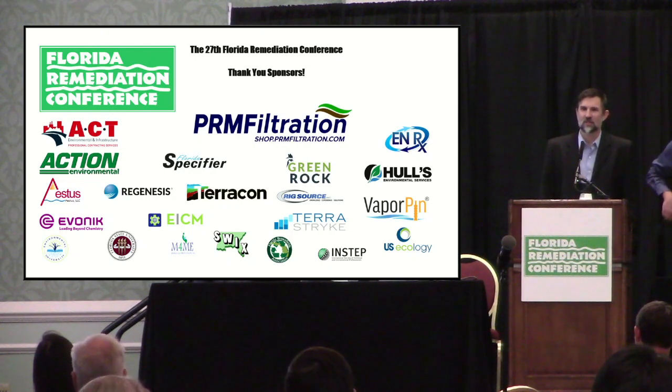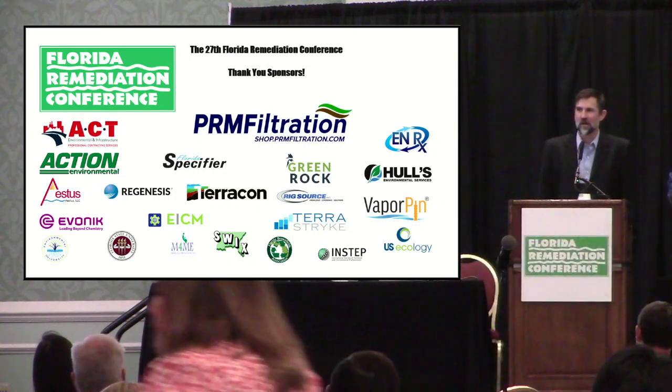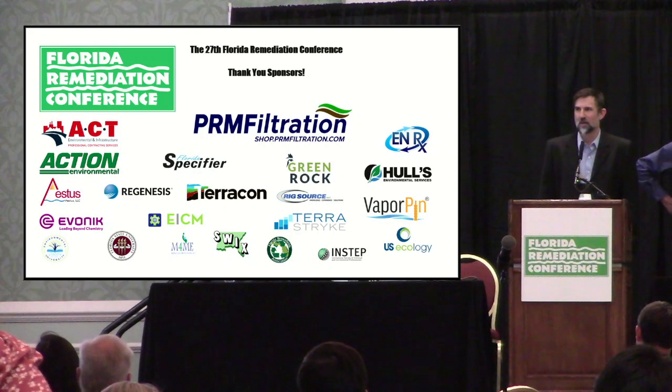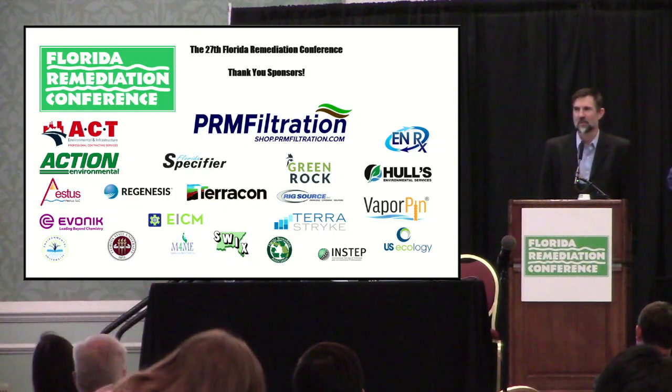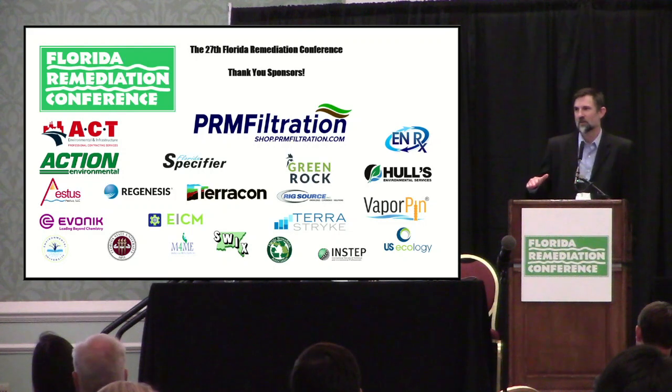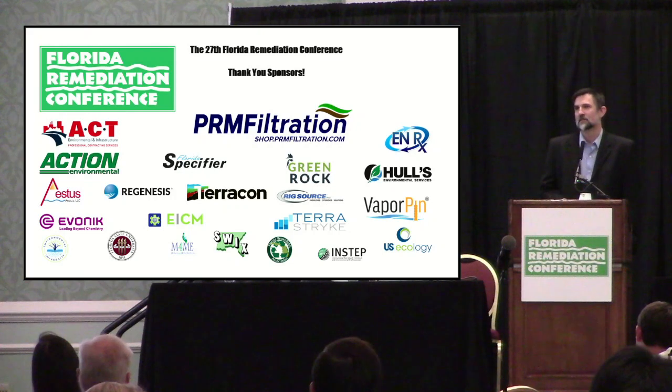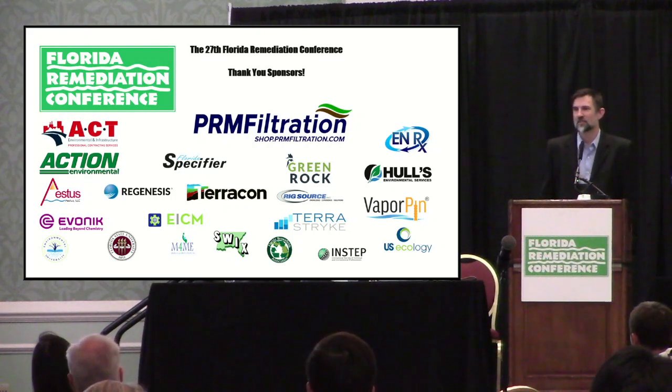In some ways, depending on the survey methodology, the structure from motion might actually be a more accurate estimate of an irregular waste pile, just because depending on the survey methods, you might not get every undulation that you do with the structure from motion method, where you're going to have maybe around 40 points per meter, or 100 points per meter of your point cloud data. So in some ways, some of these technologies are probably more accurate than some of the traditional methods. Does that answer your question?